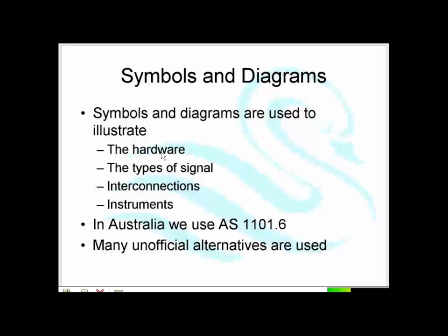So, when you get a set of P&ID drawings, as they're called, generally you'll find a few pages on the front of the set of drawings, and they're like the glossary. That's the index, and that's the symbols that the person who did the drawing has used.